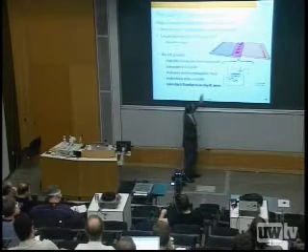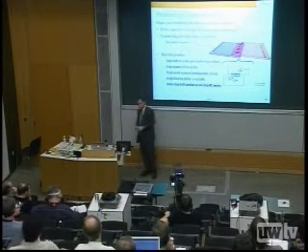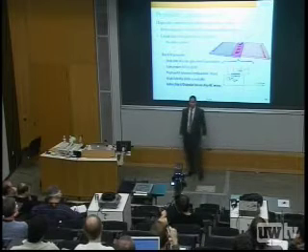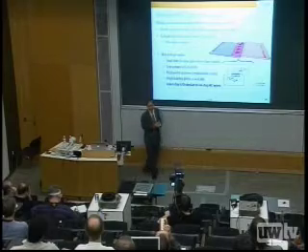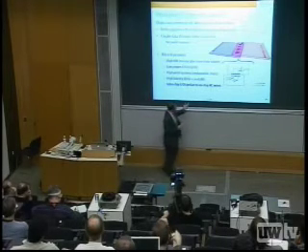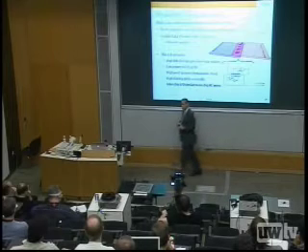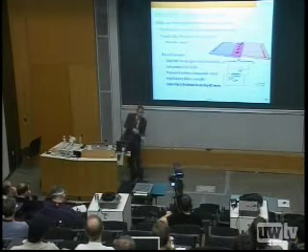Now, what's interesting about this is, well, they're small structures. They're really small structures. The density of this bandwidth is easily 40 to 60 times more dense than area solder, C4 style solder, for example. They're small structures, so the power I consume to transmit data is relatively low. I can do 1 picojoule per bit, same thing as 1 milliwatt per gigabit per second, so it's relatively small